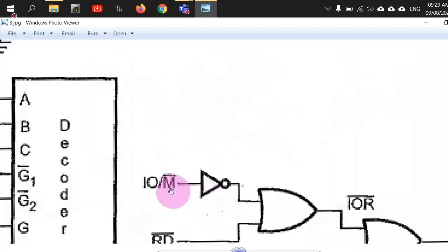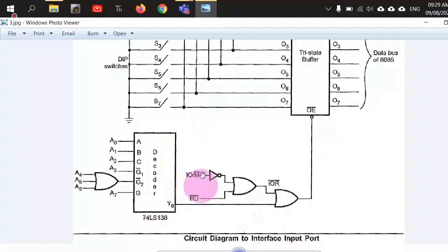You can notice here that for this hardware circuitry there are these A0 to A7 pins, right? So these are address lines A0 to A7. The rest of the address lines, from A8 to A15, are just a duplicate version of A0 to A7. So in IO mapped input output mode, you give the address bus not the complete 16-bit address but only an 8-bit address, and that 8-bit address is duplicated onto the lower order byte as well as the higher order byte of the bus. So you can use any pins, either A0 to A7, or you may also use pins from A8 to A15 for the purposes of addresses.